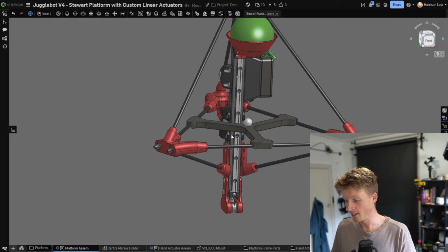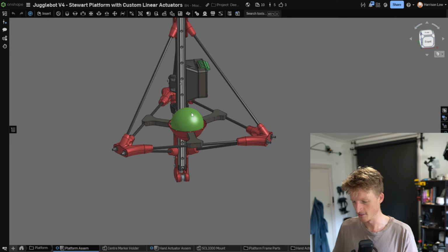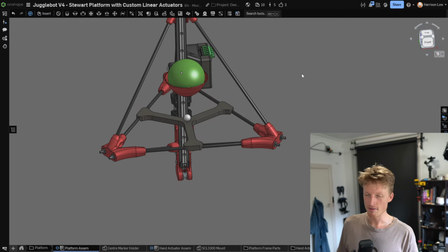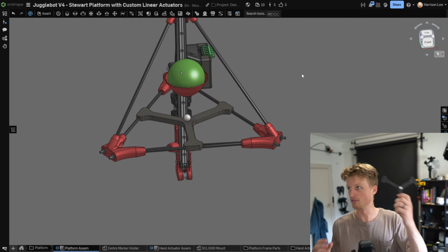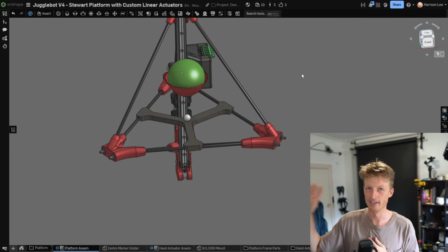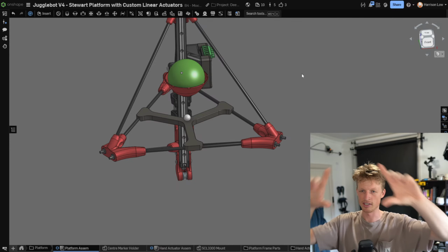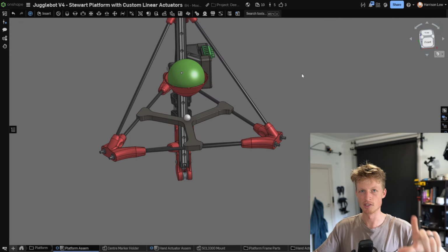Of course, we can't leave this little frame in when Jugglebot's in actual operation because the hand is going to smack right into it. However, that doesn't matter because we only need to have this little frame there when we're doing that first initial calibration or recording. So we take a recording of where all the markers are, and then in the tracking software, we can select a bunch of markers and say, yep, these markers make up this rigid body.